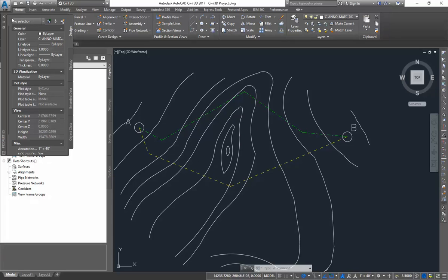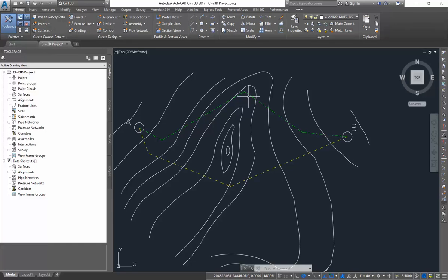So the first thing that you're going to do, I'm not going to lead you through all the steps, is you're going to define an existing ground surface. You're going to follow similar steps where you create a surface and name it, and then add surface data by going over to the Prospector menu, and under Definition, finding Contours and adding all 11 contours.